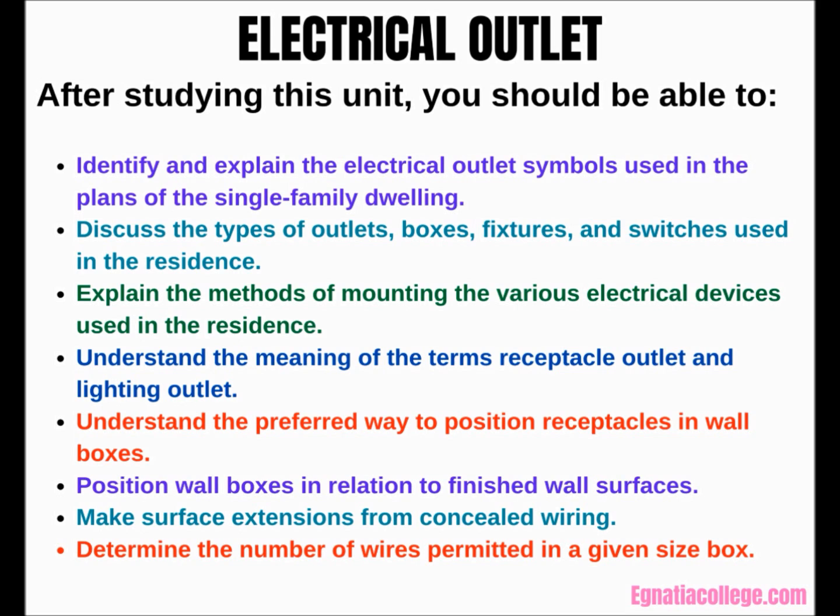Position wall boxes in relation to finished wall surfaces. Make surface extensions from concealed wiring. Determine the number of wires permitted in a given size box.